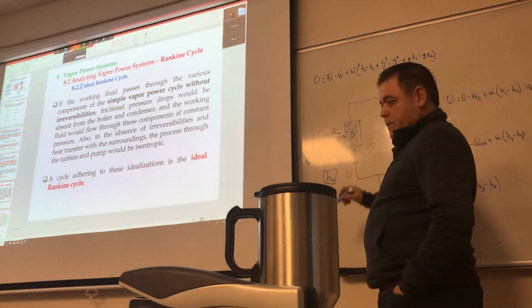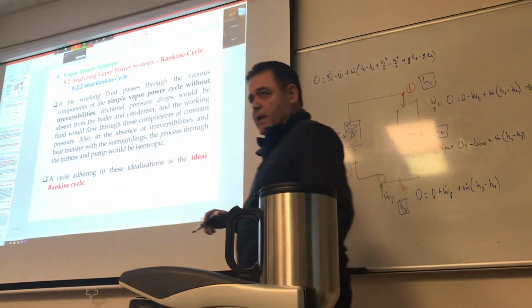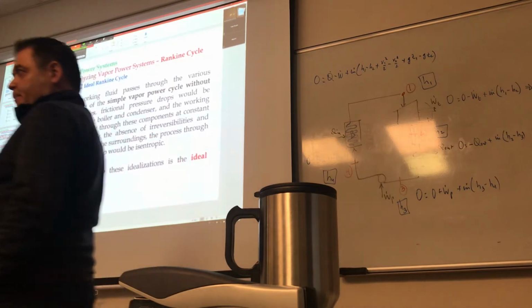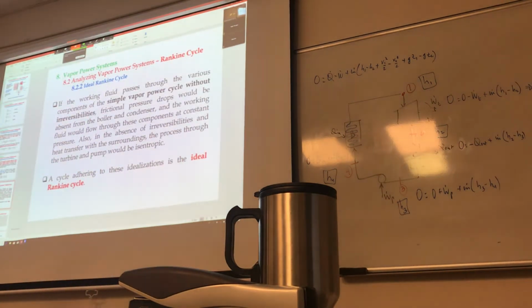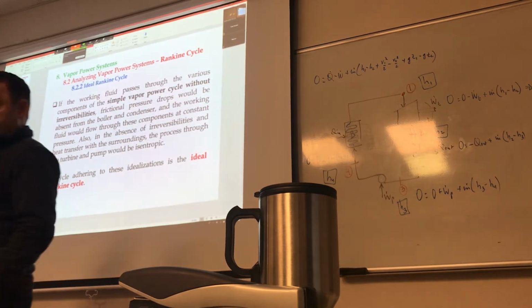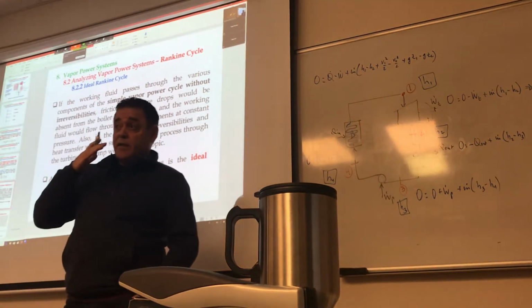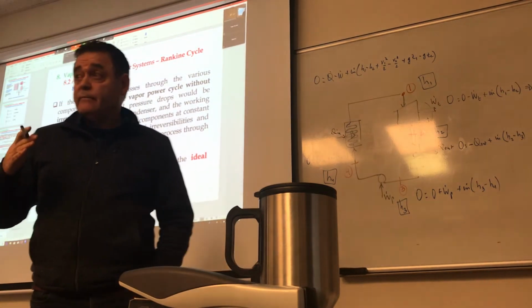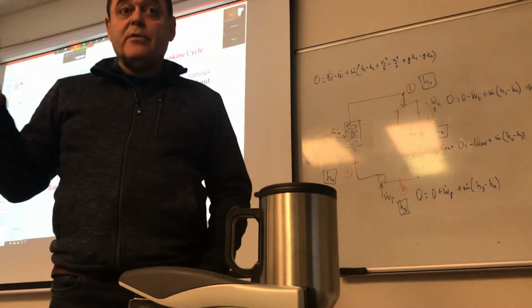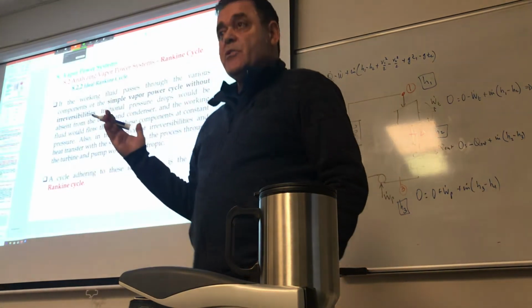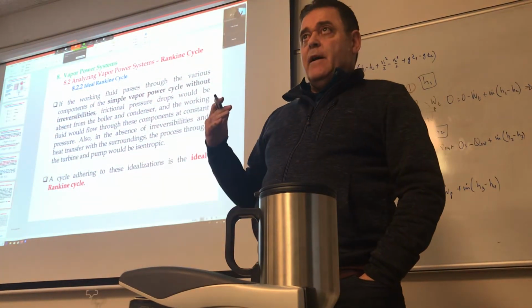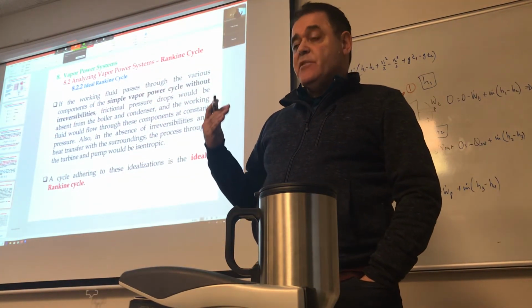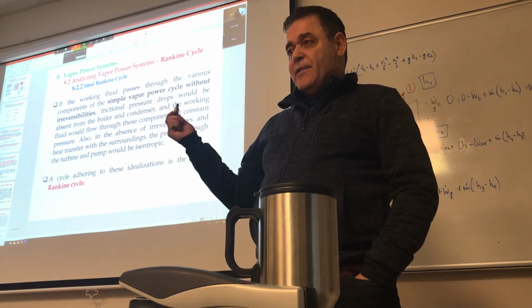And for those of you who have taken or who are taking fluids, you know that if fluid is flowing through a pipe, even if it's a horizontal pipe, just to make a simple assumption, is there any pressure loss between the inlet and the outlet? So at the inlet, the pressure has to be higher, right? That's what causes the flow. That's what sustains the flow,